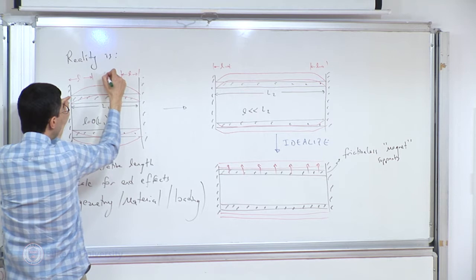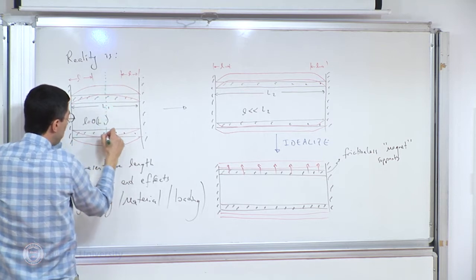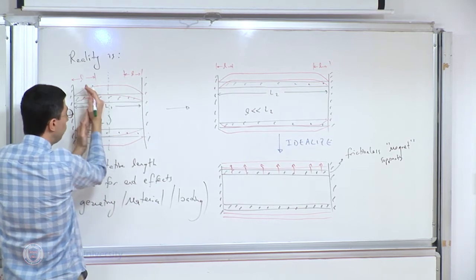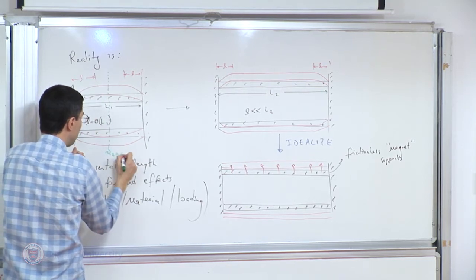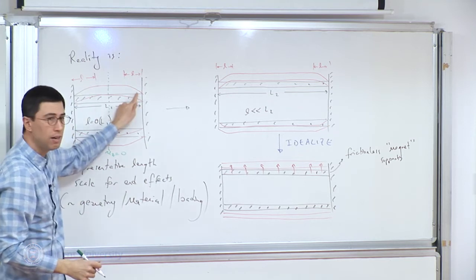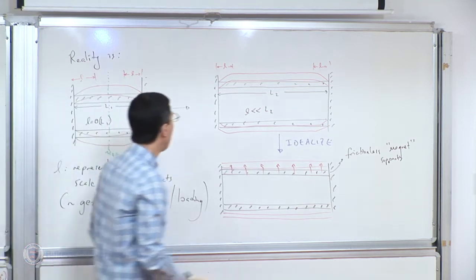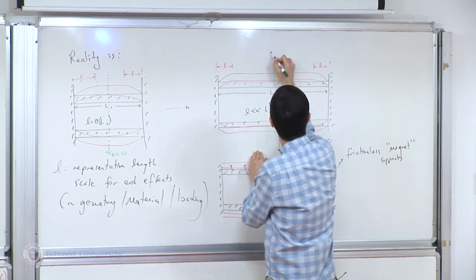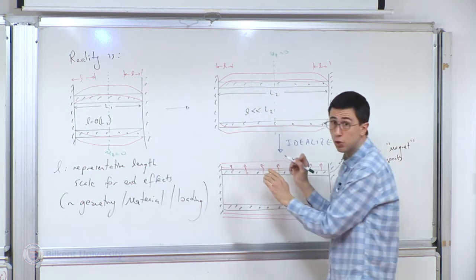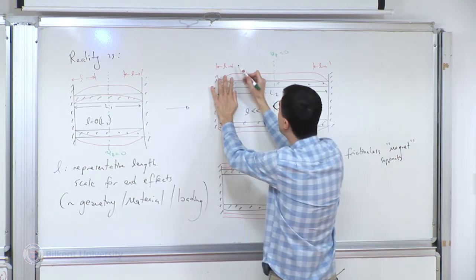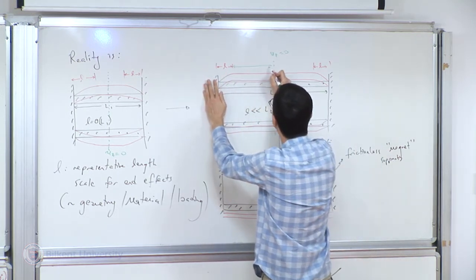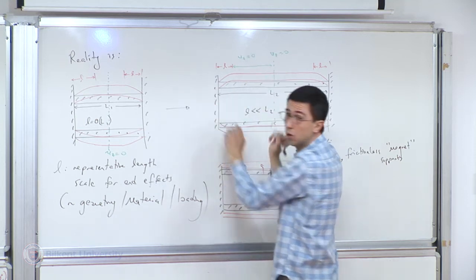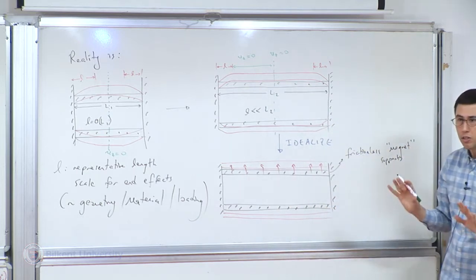Now, due to symmetry, right across the middle, right there, this point cannot move left or right. So for sure here, uz is equal to 0. But here or there, it's not going to be 0. We'll see. As you make it longer, what we will observe is that here uz, due to symmetry, is for sure 0, but away from the end regions, in other words in this region, we will see that uz is also almost equal to 0. This is just an observation.